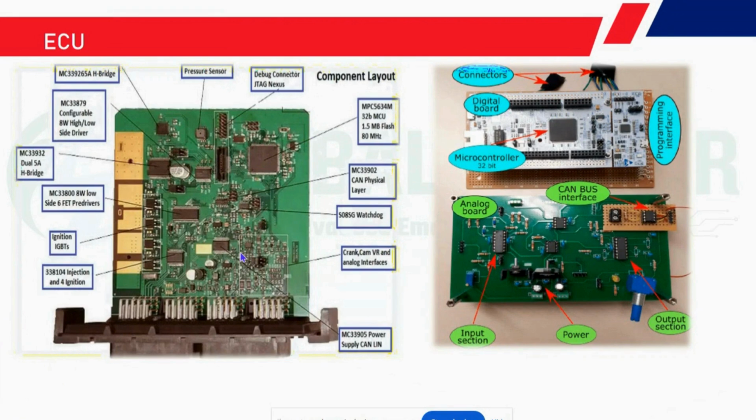Internally, we require some protocols for debugging purposes, and it has some interfaces that can be configured specific to the ECU, which are essentially required for flashing the software, debugging the software, and saving data in the memories, the NVRAM memories. Those are essentially the components. It will be part of the application of the microcontroller.